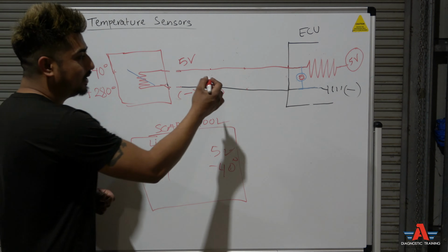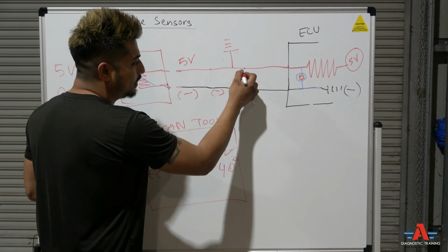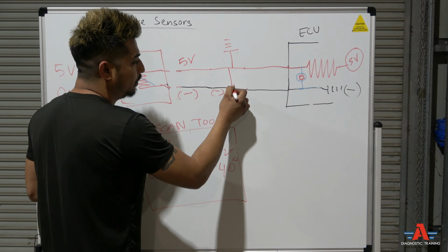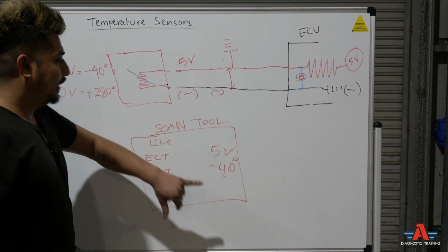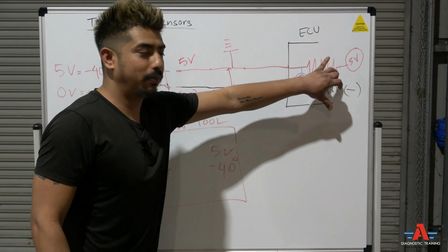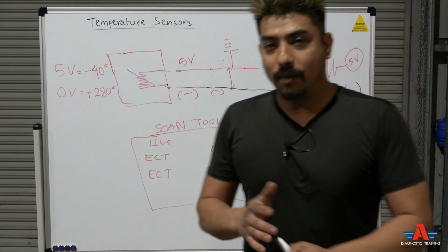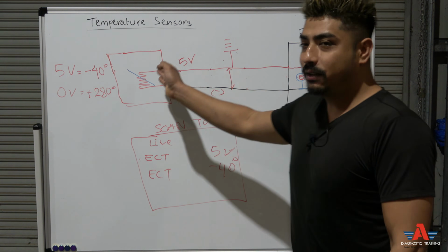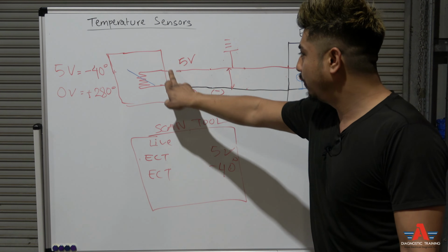Another scenario, let's say this is shorted to ground, or you can say it's shorted here, whatever the case. If you disconnect the plug, nothing's going to change, like I said. Now, where is the problem? Is it the computer or the wiring? Now you're going to have to pull up a wiring diagram. Up until that point, you don't need any information.